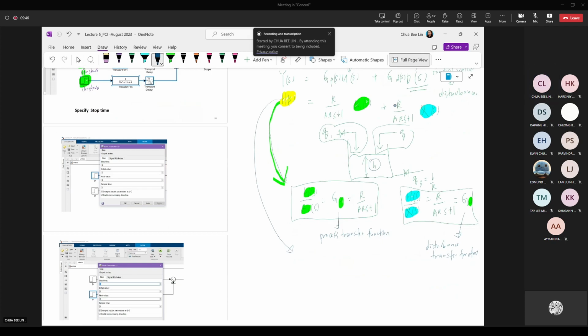So if you want to draw this block diagram, you'll be having two blocks, one for Gp, one for Gd. The input for the Gp is Q1. For this example, it is Q1. And for this example, the input for this is Q. Okay, and both plus together contribute to your outcome. So I put the scope over here. My outcome is my H level. So this one will be the H. So this is the one we have, the open loop response.